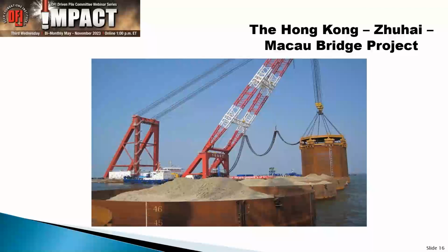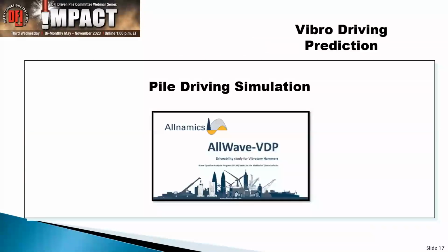So when we are thinking about vibratory driving, it's a little bit more complex than pile driving with an impact hammer, because other than the soil, the pile, and the hammer, the three elements that you need to model, you also need to model the hook load and keep control of that. And again, we'll come to that a little bit later. That hook load is absolutely essential. So, first step then, pile driving prediction.